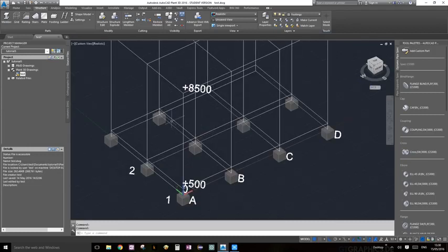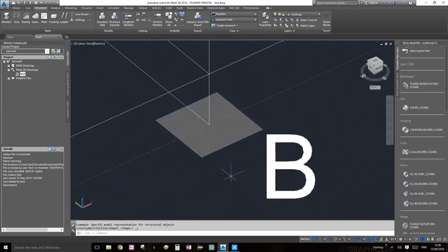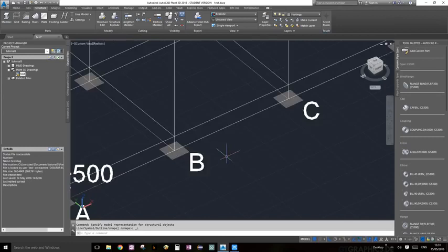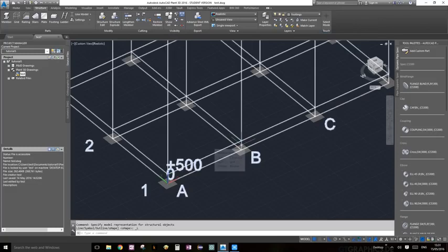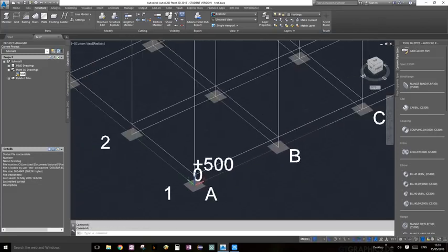Now here I will show you an important thing. If you go on the structure palette again and to the parts section, there's a little drop down box here that says shape mode. It's on shape mode. If you go on line mode, it will only show a cross-sectional representation of your footing or any structural member, really. One huge advantage of that is if it's not the actual 3D representation, then you're able to select all the points, all the nodes, easily.